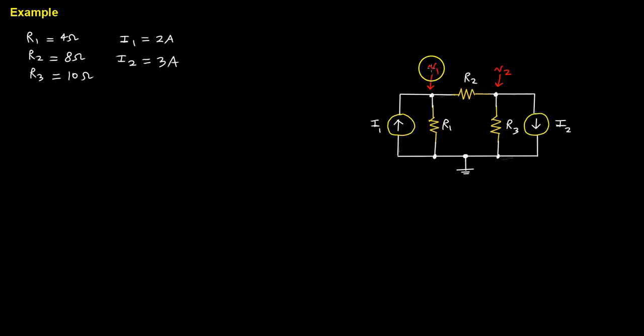So we have to find the voltages V1 and V2 through nodal analysis and the linear algebra techniques that we talked about. The first thing I'm going to do is assign some direction for currents, and this is completely arbitrary so long as we keep the interconnection of nodes consistent. So the current going into them should be consistent with the current coming out of a different node. So I1 I'm going to say is going to be entering this node, and the remaining currents are as such.